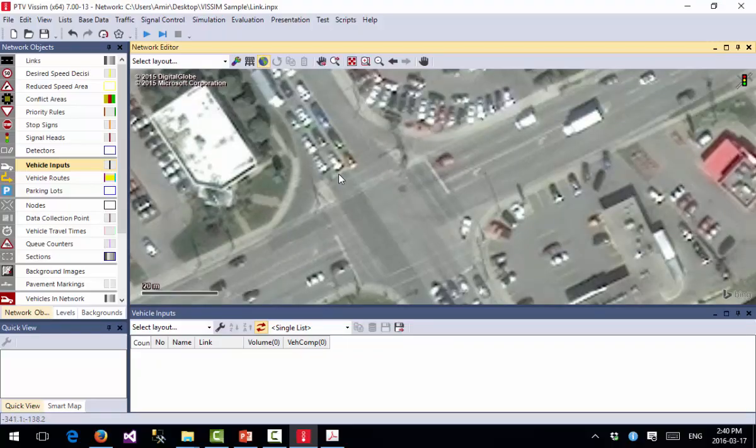And I suppose that for the simplicity of our network, I will assume that we will have these two signal phases. One for the northbound, southbound, and one for the eastbound, westbound on University. If we do that one, we can do the other things. We have some kind of curve around the intersection here. Sometimes it's a very good idea to go and walk in the intersection if you want to model it. If you don't have access to that, use Google Street View, and you can move there and have an idea how the intersection looks like. So we will try to model this intersection.